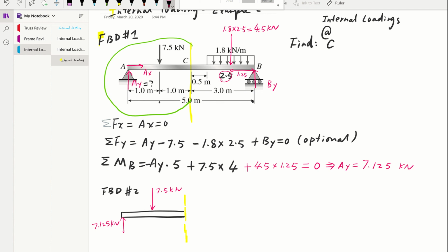How about internal loading? So we're reviewing the internal loading. Using the sign convention, tension perpendicular have to be normal and have to make it tension, right? The normal have to be in tension, so that's going to be N, pulling apart. And then we also have shear. Shear is going to make this entire structure rotate clockwise.